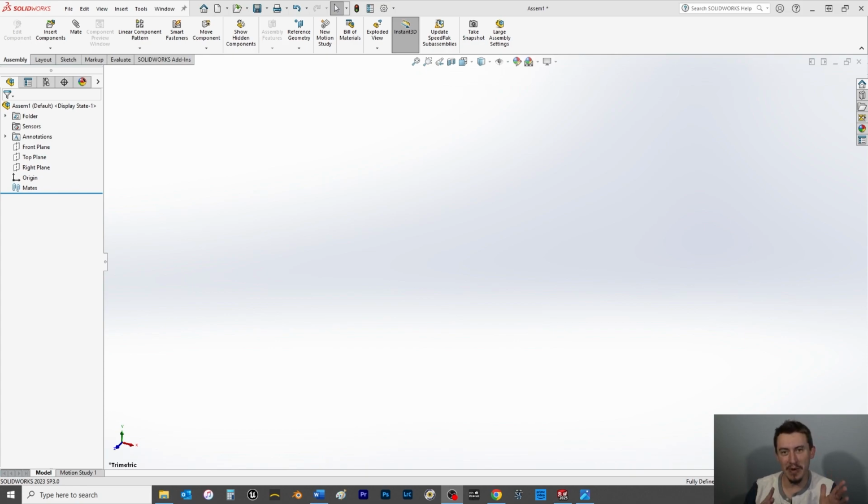again, you'll want to make sure that the parts are all in the same file folder. It's not necessary, but I can tell you that you will lose association real quickly if one of those parts gets moved around. You'll have to reassociate it. In other words, if you open an assembly and you've moved a part to a different folder, it will let you know it doesn't know where this piece is. Do you want to locate it? It gives you a certain amount of time, and then if you don't locate it, then it suppresses the part and basically omits it from the assembly.